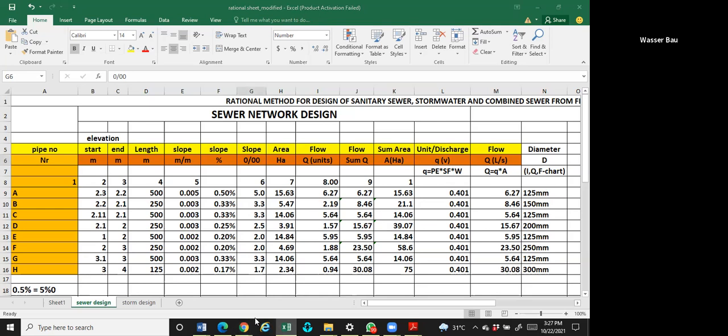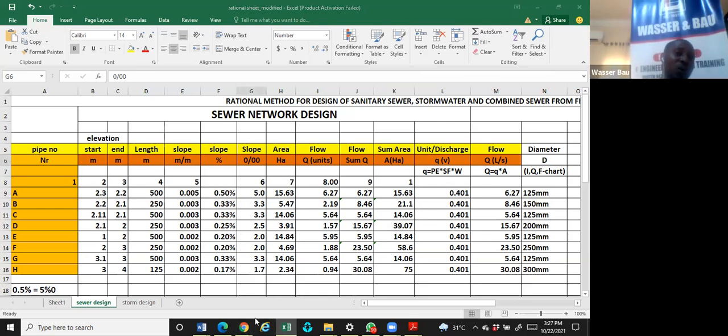In fact, if you want to do good infrastructure work, be it sewer, stormwater, or telecommunication, they should have done the road design. The road design should have been done because you have to follow the right of way. And the road design, even the cut and the fill, will follow the road level. So here, in real life, column B and C should be the spot height.